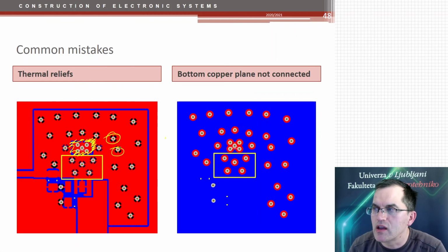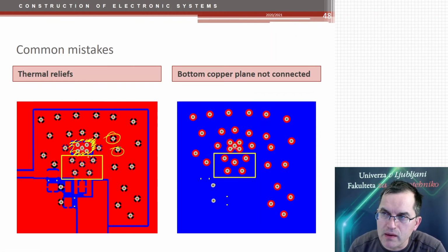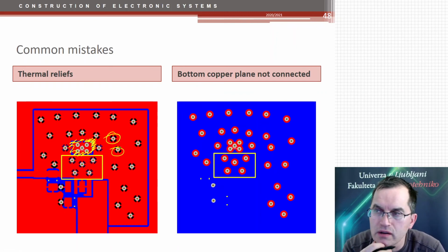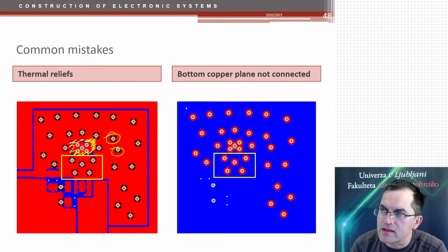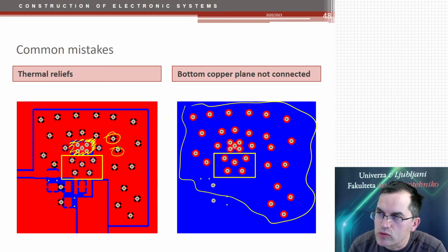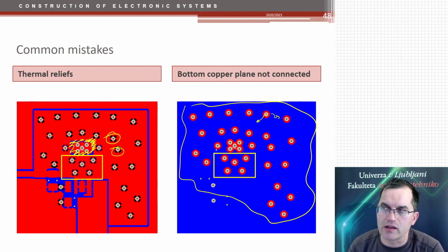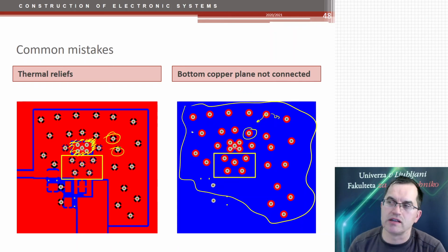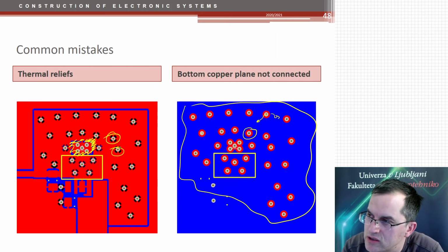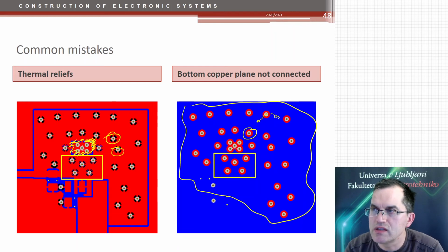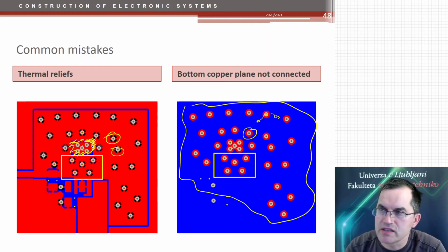And on the bottom side, you may forget that this cooling pin is not necessarily on ground. It could be on other potentials. Therefore, you have to provide this area on that potential. Don't just do it like that, because these wires would have really deteriorated heat transfer laterally if they are not connected directly with copper. They are isolated from the most conductive material here. So please do not make these mistakes.